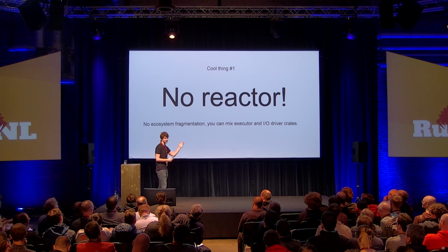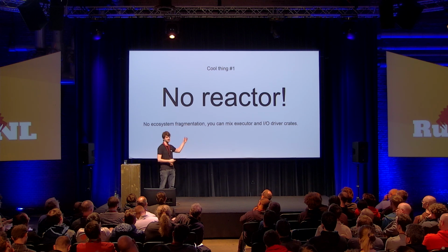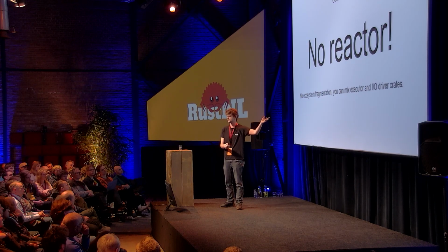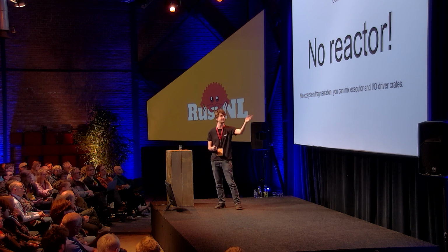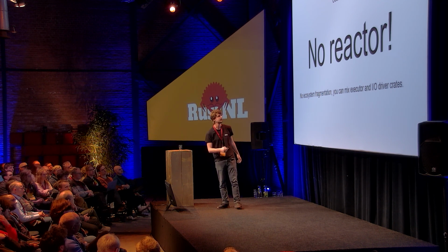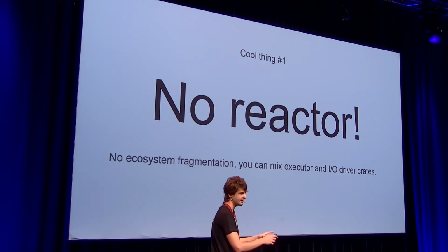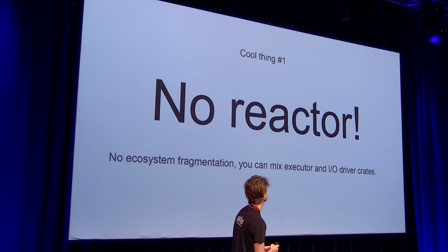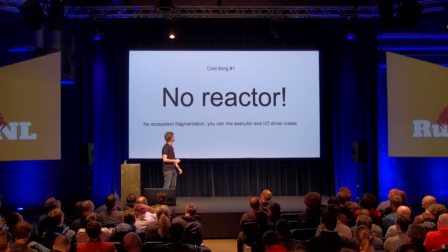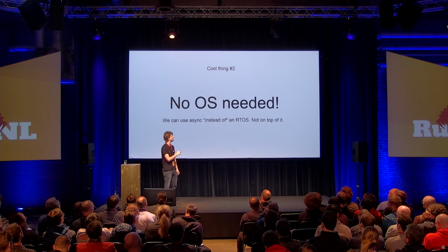This is not the case in embedded. You write drivers, they work, and they work with any executor. As long as you write your executor properly, it will be able to run any driver without having to explicitly add support for particular hardware to it. It's almost architecture independent even. If you want the executor to put the core to sleep, you have to do some architecture-specific things, but that's about it.